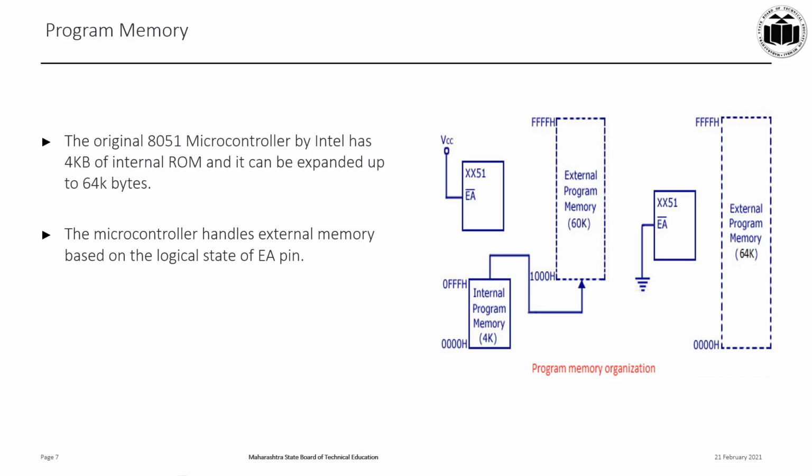In both cases, port 0 and port 2 are used for data and address transmission, and so they cannot be used as the I/O ports. Also, the pins ALE, address latch enable, and PSEN, program store enable, are used to access the external memory.